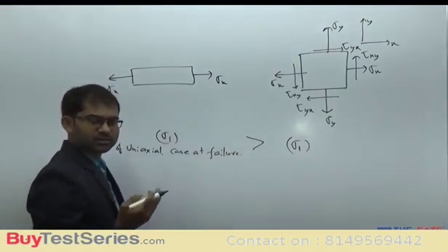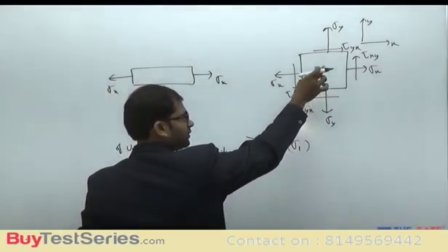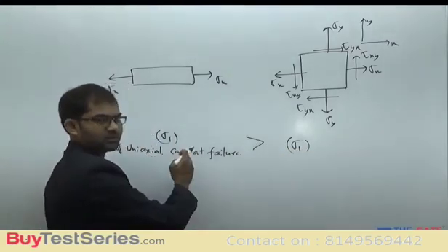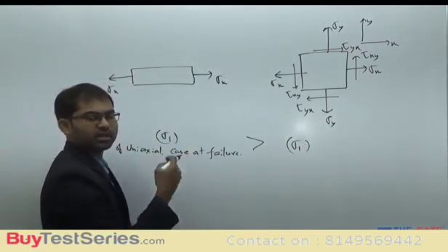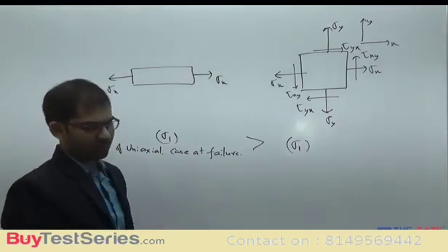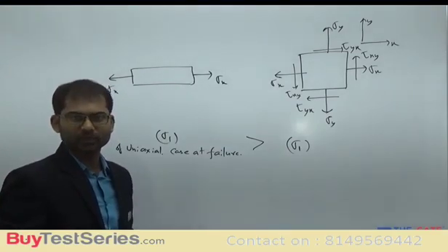For example, if it is the maximum shear stress theory, here you will be taking the maximum shear stress, and here also we will be taking the maximum shear stress of this case, and we compare. So our parameter should always come less than this value here. Otherwise, you will be experiencing failure. Later we can check how authentic it is, and for how many types of materials a particular theory of failure is valid. That thing we can decide.